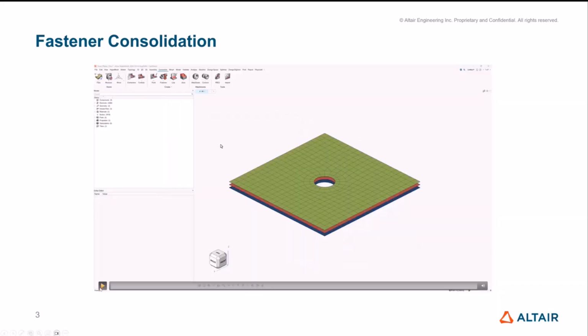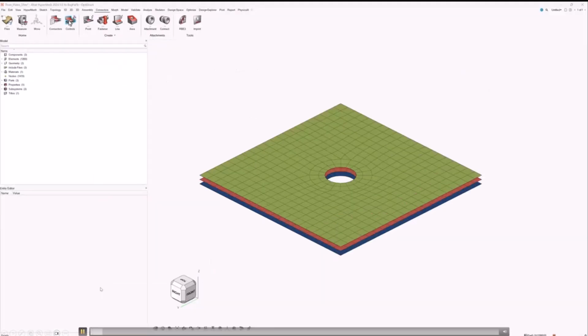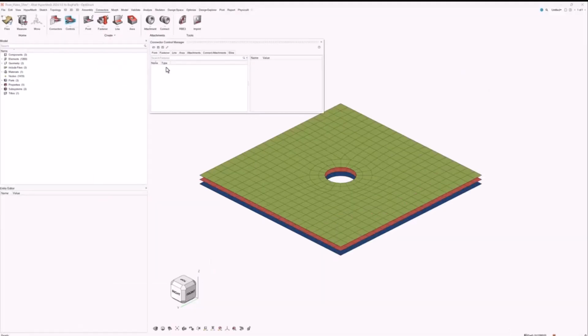If we look at a bit more of this process from a realization point of view, I can go in and define a new control. I've specified this is an M6 type realization. In this case, I've got holes, and I want to use a hole type bolt. I set my bar diameter directly within the control. I define a parameter for my pretension. I specify my body configuration: I can change the bolt length, so the length of the body, or I can turn the head on and off. In this case, I want the head.